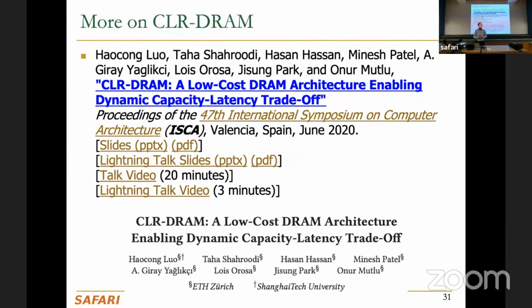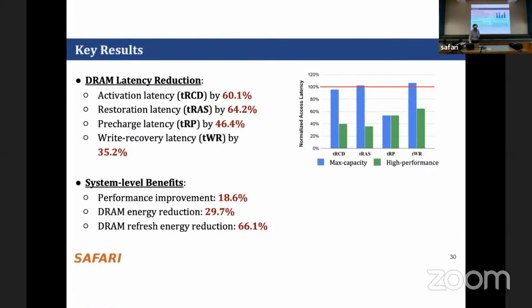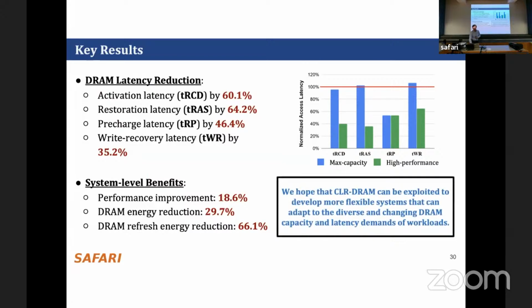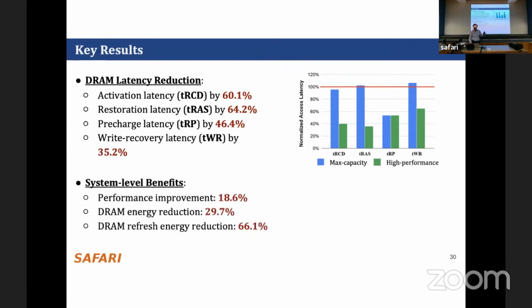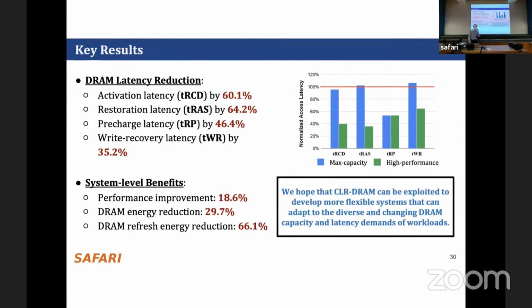Any questions, thoughts, ideas? Yes. Sorry, I don't get why we have a DRAM refresh energy reduction. Yeah. So basically now you have much stronger cells because you're coupling things, right? One cell may be weak, but the other cell may be strong. That is part of the benefits. There's some more, but it's discussed in the paper. So that's the beauty, right? Once you're coupling cells, you actually get a lot more benefit. So there may be even more ideas in DRAM refresh that this could inspire.